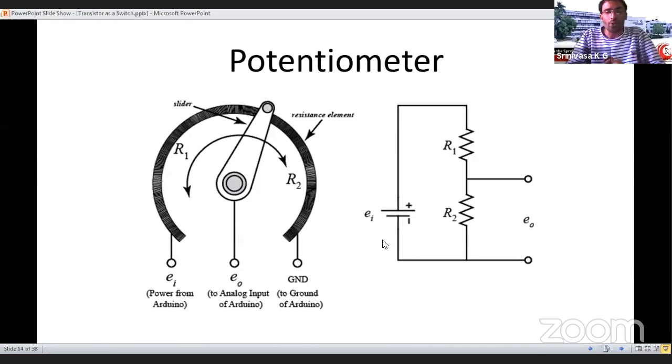A microcontroller reads any signal in the format of voltage. So how we can convert that resistive signal into a voltage is very important. If you understand that conversion, then you will be familiar with 70% of sensor interfacing. It is very interesting and very useful. Why is it useful? Because 70% of sensors are resistive type. If we talk about the FSR, force sensitive resistor for force measurement, the potentiometer, the LDR, the flex sensor, all are resistive type.